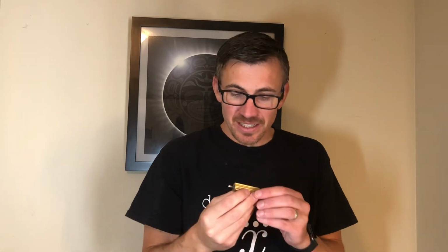A typical resistor, like this little one right here, typically has a 1/4 of a watt or 1/8 of a watt power limit. If you want to drive more current through it, if you want to dissipate more power, this is one such example here. It's got a heat sink for a case, which is just designed to dissipate a lot of heat. And according to this, it can do 50 watts. So this one can dissipate a lot of heat. And they're usually used for testing loads as they're called.